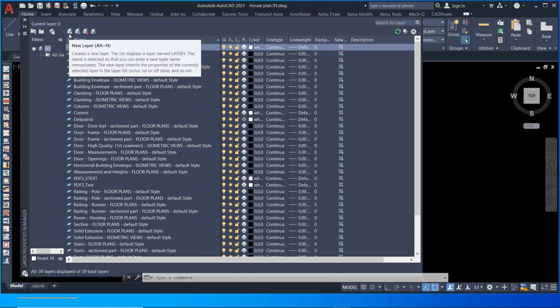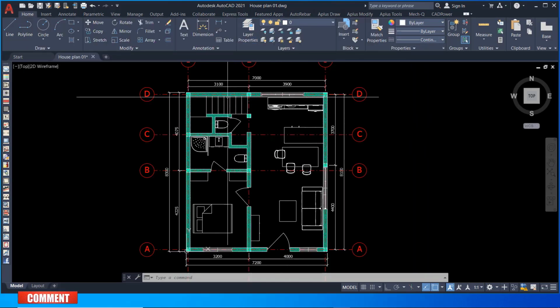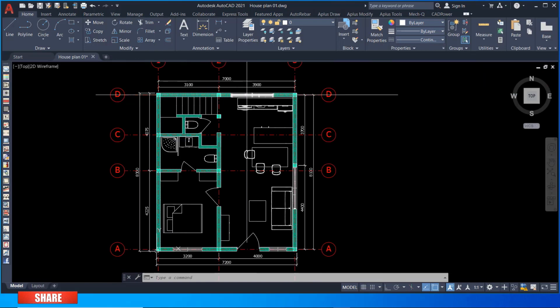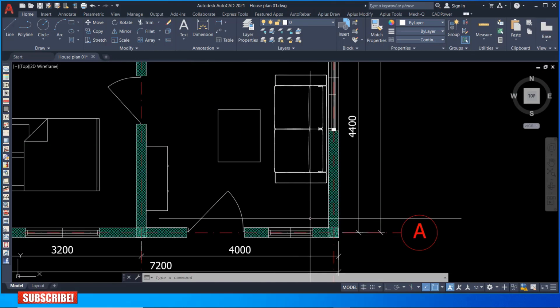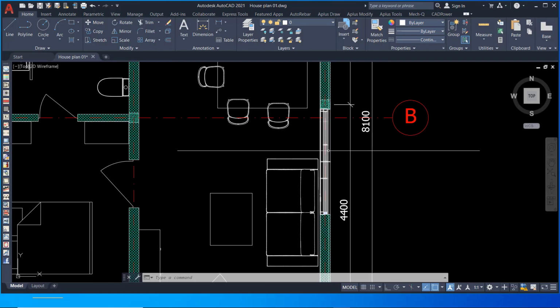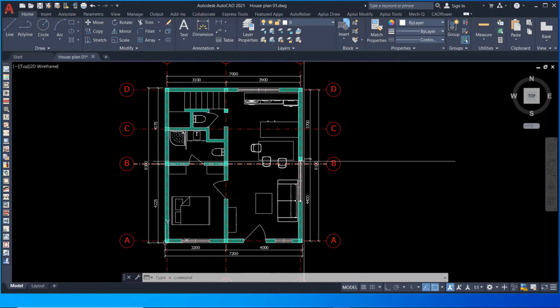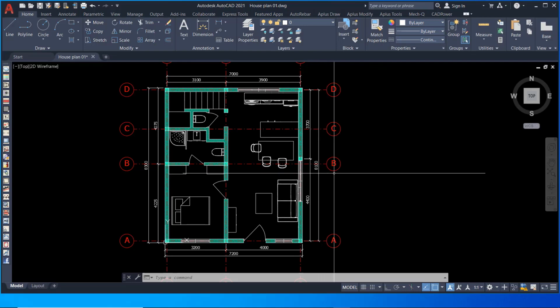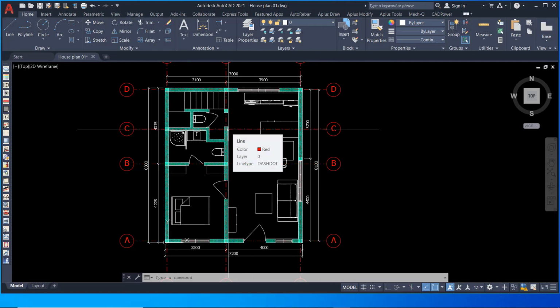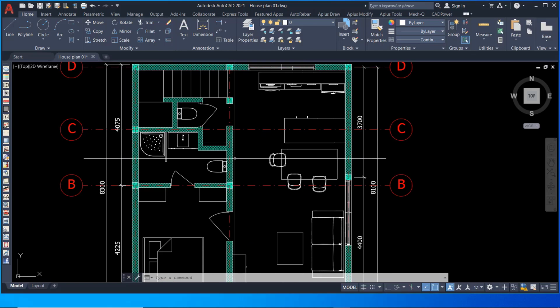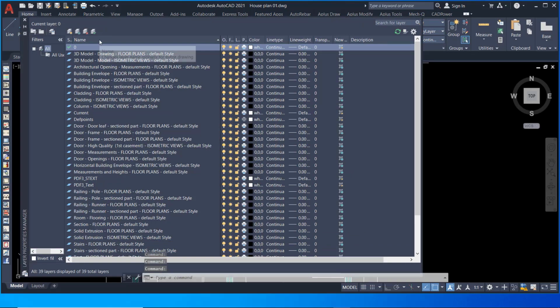of those particular parts that we find very necessary. Like in our case here, if I go back to the plan, you see we have the walls, we have the windows, we have the internal furnitures, we have the doors, we have the columns here. So we want to define or create new layers for those specific parts in the plan here, and get rid of the so many layers that we've seen under layers properties. So we'll go back to layers properties here and start creating new layers that will match with the parts or with the sections or with the objects that are existing on our plan.